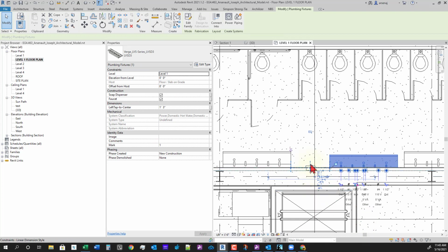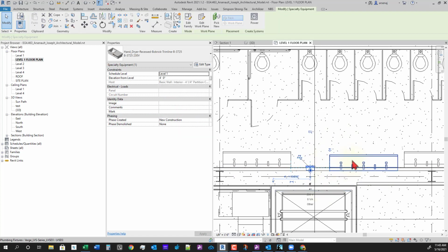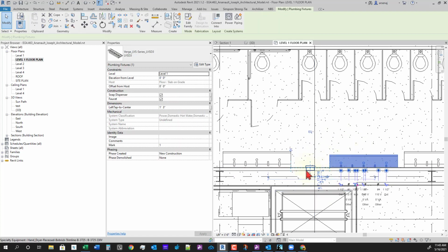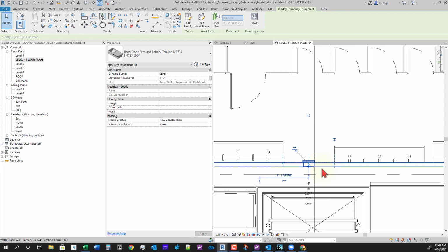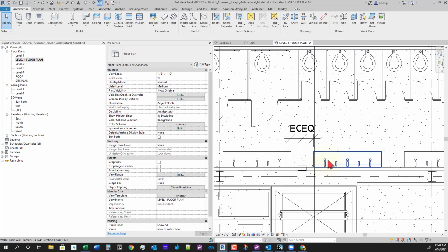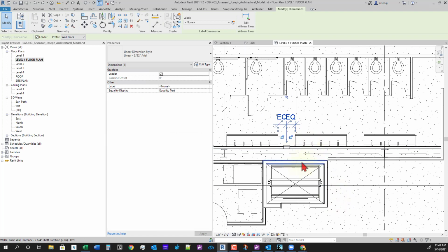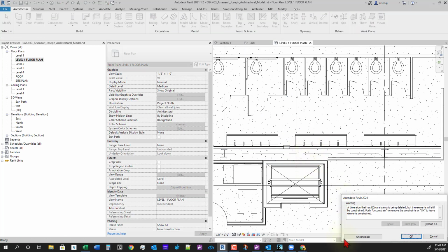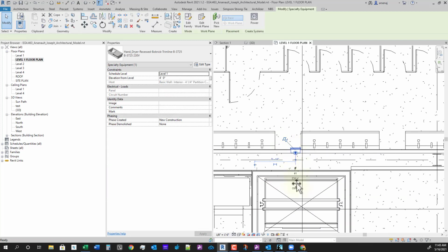It's going to keep it equal distance between there, but you can't see unless it's selected. So if you have elements selected, it's a light blue EQ and light blue dashed lines. So I'm going to hit undo. If you have equal dimension and you just delete them, you need to hit unconstrain so that it removes that equal constraint. Now I can move it without it being constrained.